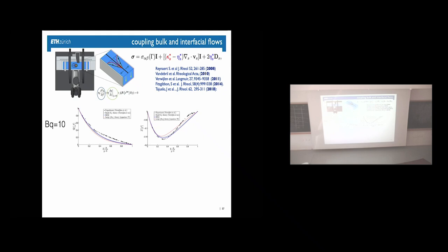And we see that the velocity gradient is higher at the needle than here. Even worse for rheologists, this is a Newtonian interface, it's a fatty acid, we know it's Newtonian. There's an imaginary component, an out-of-phase component. The stress boundary condition creates a shift between the bulk flow and the interfacial flow. So even though all is Newtonian and the phase angle should be 90 degrees, we see that there's an out-of-phase component, because the momentum transfer has different speeds at the interface and in the bulk. And so I get a phase shift even for a purely Newtonian material, which has nothing to do with material properties. It's just a consequence of the fact that I have two speeds of momentum transfer.